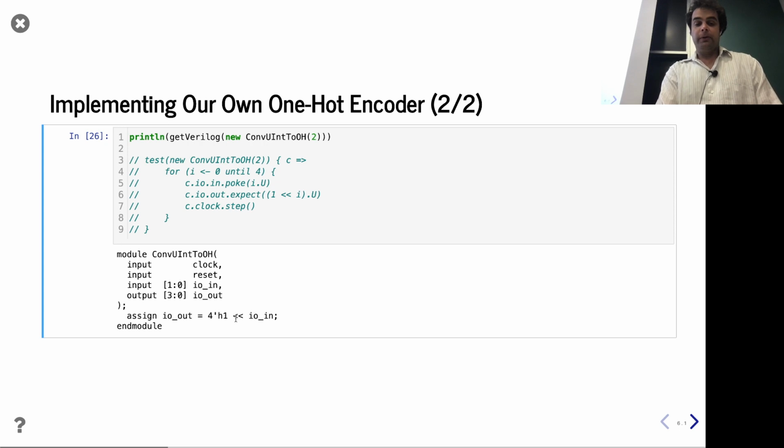And so a dynamic shifter in hardware is actually not a super cheap component. Even though it's really easy to write in Verilog, in terms of how it actually gets turned into hardware, that could potentially be done in a variety of ways. You could do that with giant mux. You could do that with many small muxes cascaded. You can do it with logic gates. There's a lot of different ways to implement a dynamic shift in hardware. But for now, that's below our level of concern. That's the ASIC CAD tools job.